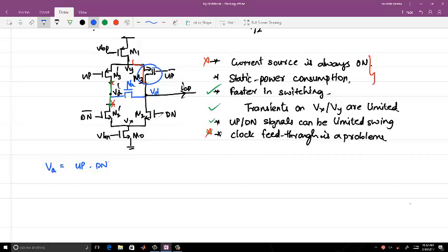What is this doing? Any delta change in VCM is going to affect the total current which is going into the charge pump. And you are switching it at every reference, so you are injecting some delta every time. So that might not be a good fix for this. Okay, so let's remove this and remove this thing.